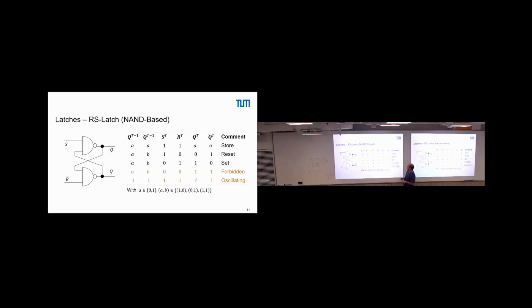Nevertheless, we can start with maybe the set and reset state. That's the simplest one. So, the set state says we have this here as 1, this one here as 0. We know that's a NAND gate. A NAND gate at the output, if one input is 0, should be 1. So then the input here is a 1, and we have here 1. So the output is a 0, right? Should be.